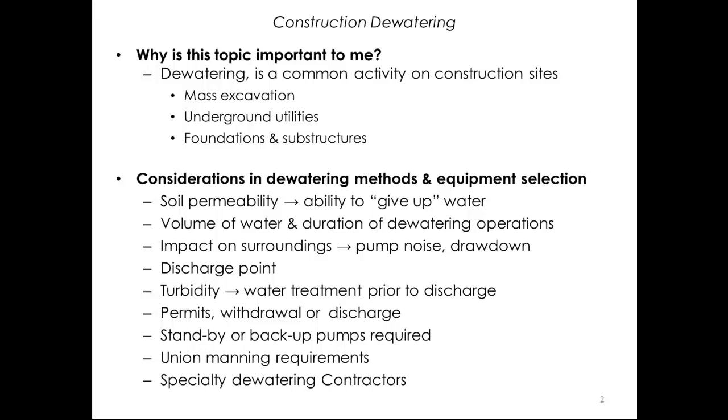Additionally, working in a union environment, realize that the operating engineers will usually claim and require that an operating engineer be assigned to gas or diesel pumps. Electric pumps, on the other hand, do not require manning by any union personnel. And lastly, know that there are specialized dewatering contractors available across the country.